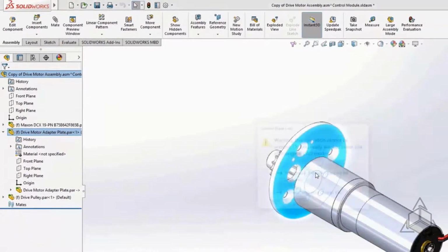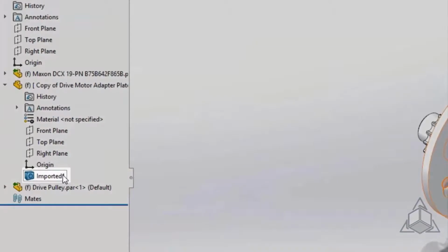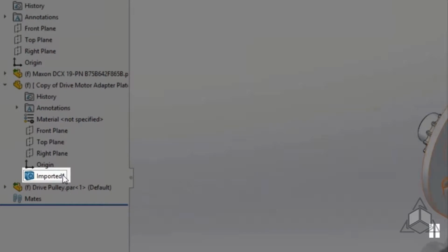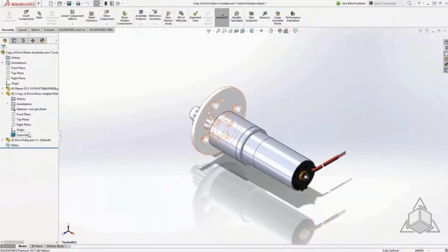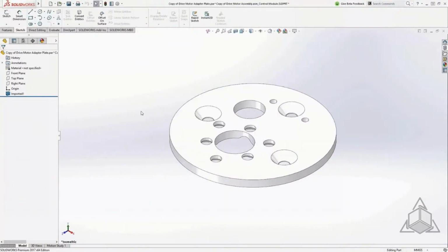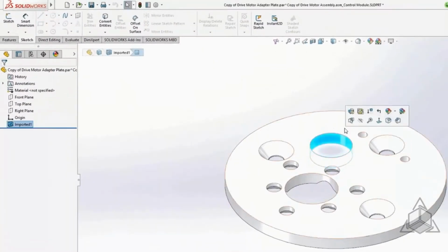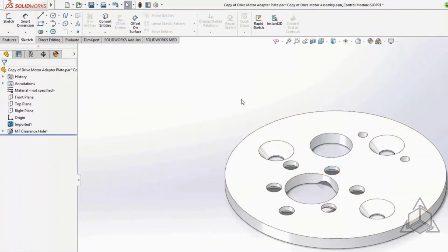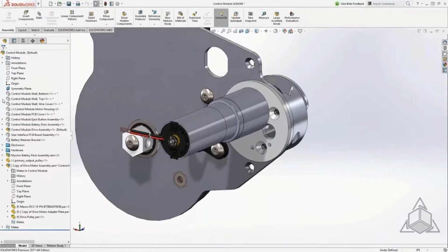If I break this link, that allows me to see what we traditionally see with an imported model. So this is using the file open import capability of SOLIDWORKS, just like we had before. It basically turns on that import, and there we go. Now, once we have that disconnected, you can see the other two components are still connected to the external files. I can now come in here, run FeatureWorks on a hole, and get feature history built back into the model. In this case, I just right-click, edit feature. That builds in the FeatureWorks hole directly into the imported model.